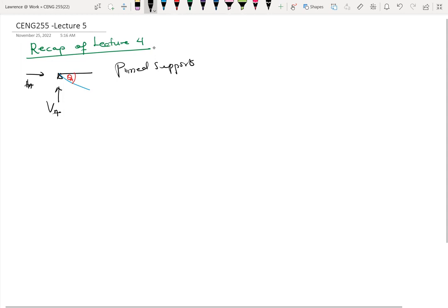Okay. So if you look at the hinge of a door, because of the presence of the hinge, the door cannot move upward. It cannot be pulled towards you or pushed towards the frame because it has resistance against horizontal motion. But you can open and close the door. And the reason you can open and close the door is because the hinge cannot resist rotational motion. All right, so the door is able to rotate towards you and then rotates back into place. All right, so that rotation definitely will lead to a slope or an angle being formed. All right, so that angle is theta A.